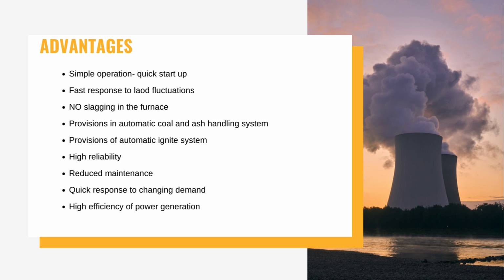Quick responses to changing demand. A fluidized bed combustor can respond to changing heat demands more easily than stoker fired systems. This makes it very suitable for applications such as thermal fluid heaters, which require rapid responses.